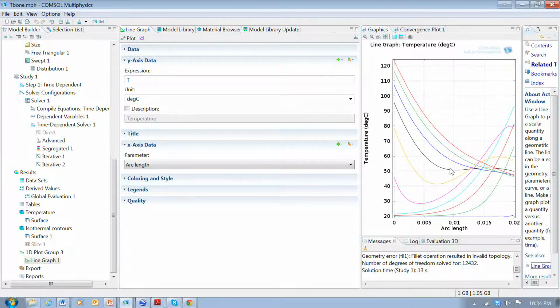So just one final comment. In this simulation, we've got this zone right here where we're predicting that the temperature is above 120. Now, if we adjusted this model so that we included the boiling of water, then we would have water stored in the meat, and when it reached 100 degrees, right between the black and the blue time periods, the heat transfer across the boundary would be absorbed, basically consumed, by the latent heat.